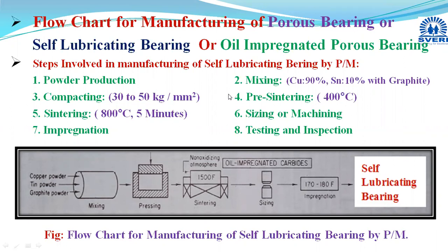I will repeat again how the actual lubrication occurs. When the shaft rotates at high speed, that bearing will get heated, meaning frictional heat will be generated, and due to that frictional heat, the viscosity of the oil decreases. Due to the rise in temperature, volume will increase and it will start coming out. It will become thinner, and whichever oil is there will start flowing on that rotating shaft, and lubrication is provided.